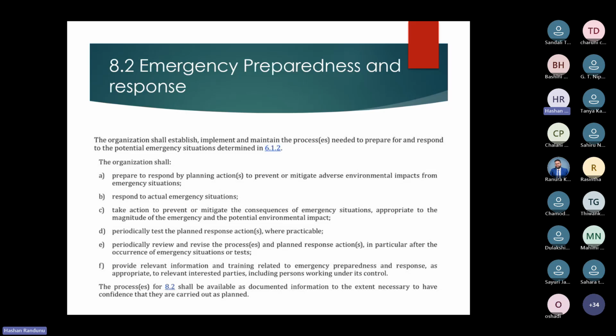If there is a possibility for that chemical contaminated wastewater to flow into municipal drainages through our inside drainages, we can implement a mechanism to close those internal drainages to prevent the water entering the municipal drainages, right? So then in that case, we have to plan how we close those drainages, right?